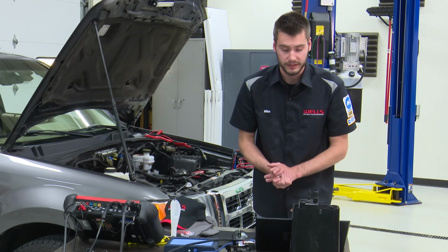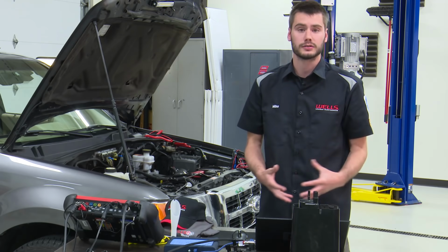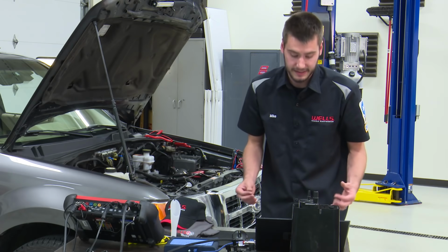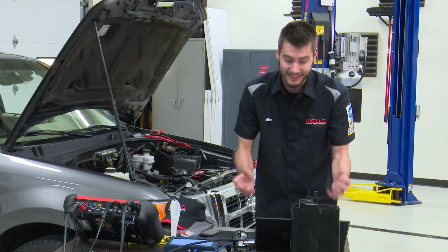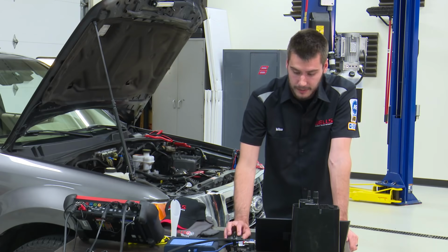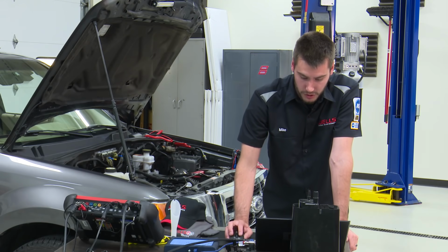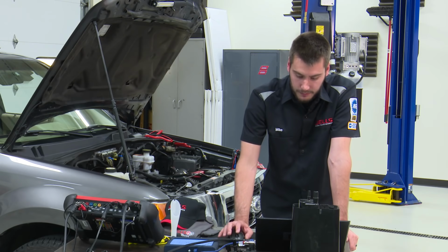But at some point, that charcoal canister becomes saturated. Those fuel vapors potentially overcome the capacity of the charcoal canister, and they need to go somewhere. We have to get rid of those vapors. That's when we open up that purge solenoid. So then we would have something that looks like this.